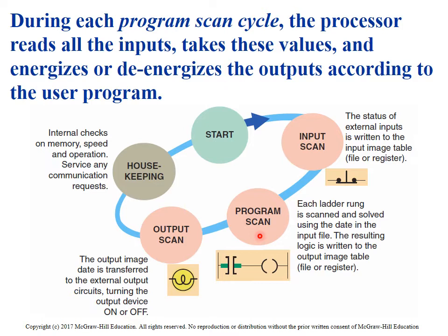And then the last piece of this is housekeeping. This one isn't always included. If someone asks what the scan process of a PLC is, quite often people say scan the inputs, run the program, and update the outputs. Sometimes they skip this housekeeping piece, which I'm flexible with, but the idea is that this is where it does diagnostics, this is where it does the communications, and all those extras that a PLC does.